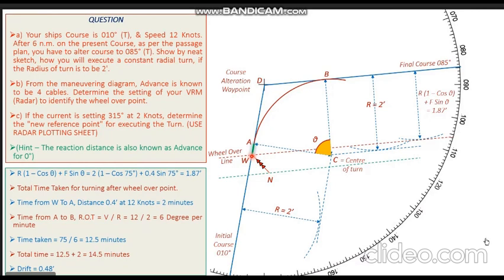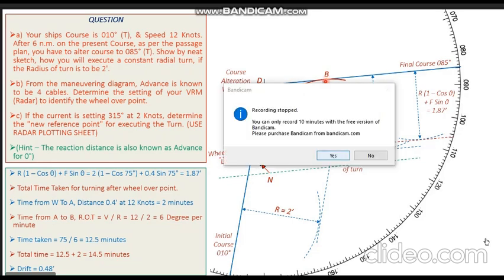The rudder action of the vessel is going to take it from W to Alpha, that is the reaction distance, and Alpha to Bravo if we maintain 6 degrees rate of turn as per our rate of turn indicator. So November to Whiskey is the effect of the current. Whiskey to Alpha to Bravo is the effect of the ship's maneuvering, the rudder angle, the helm order, and maintaining a rate of turn of 6 degrees per minute. Take a course with zero cross track error.